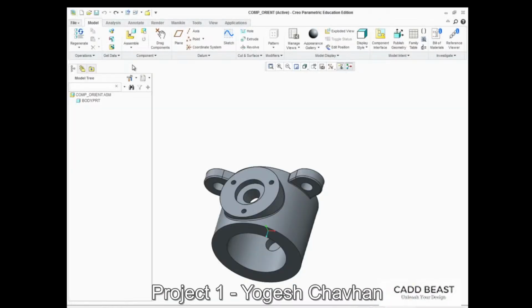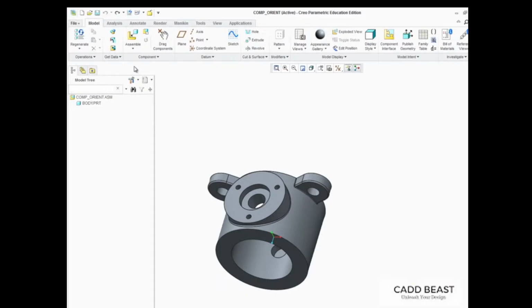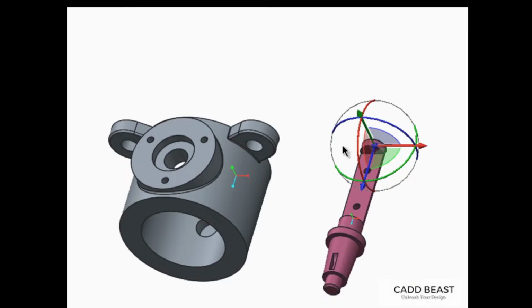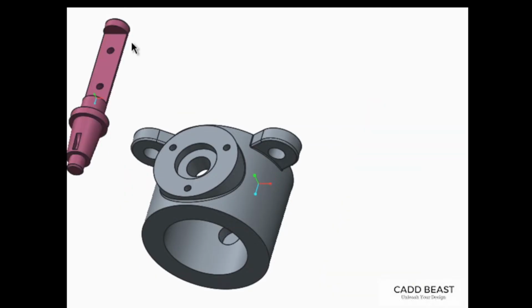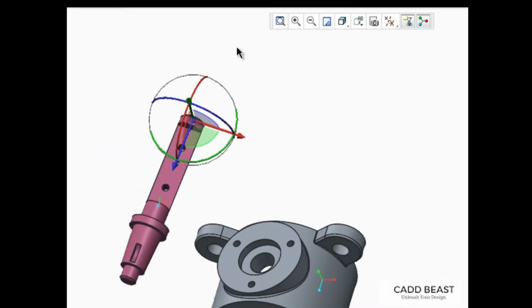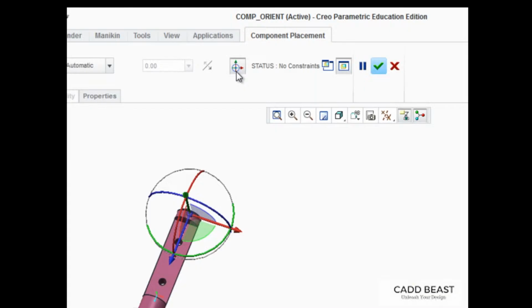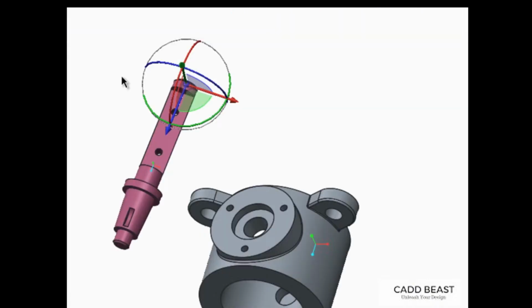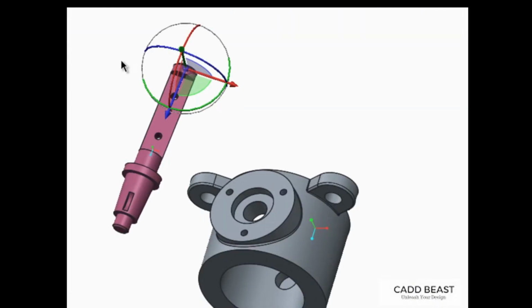Creo Parametric's Dragger interface has been added to make the process of orienting a component during the assembly process simple, fast, and intuitive. You'll see it as soon as you add a component to the assembly. Of course, you can still reorient a component by pressing the Control and Alt keys while using the mouse buttons to pan and spin within the assembly. And if you don't want to see the new 3D Dragger, you can toggle its display on and off using this icon in the dashboard. But the 3D Dragger is a much faster, more interactive method that in many cases can improve your design efficiency.